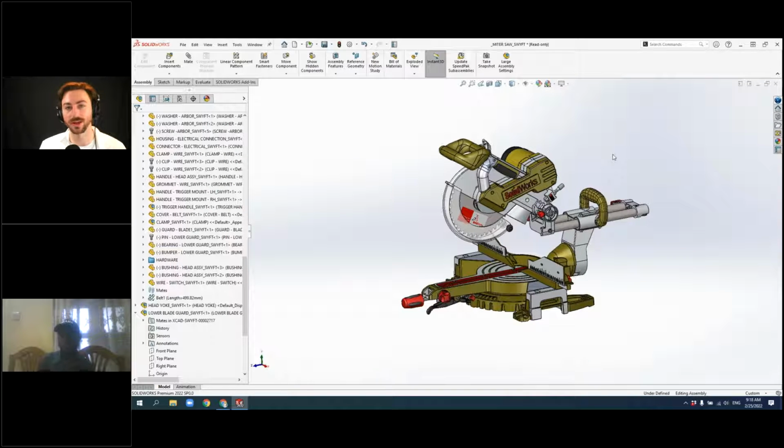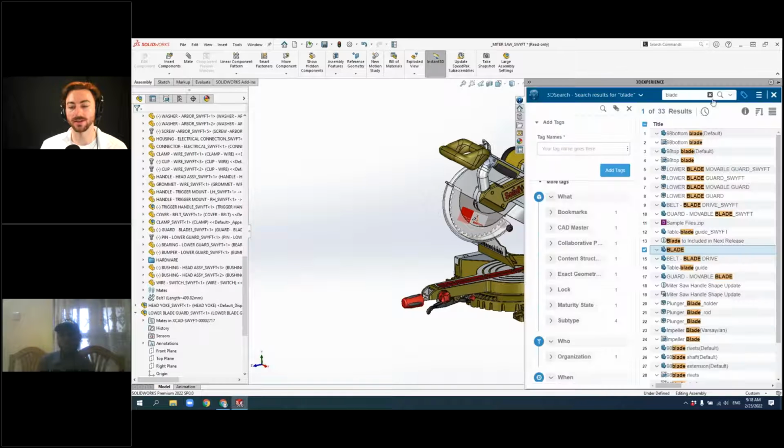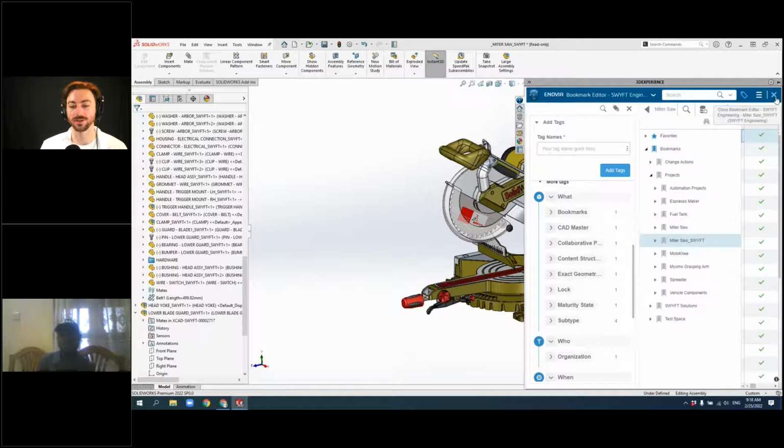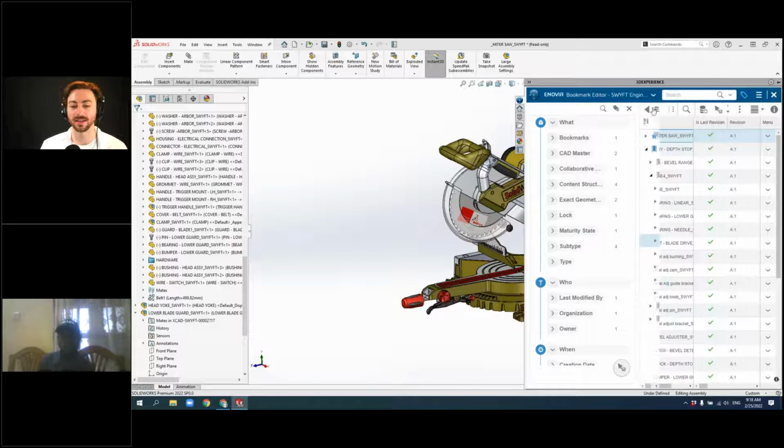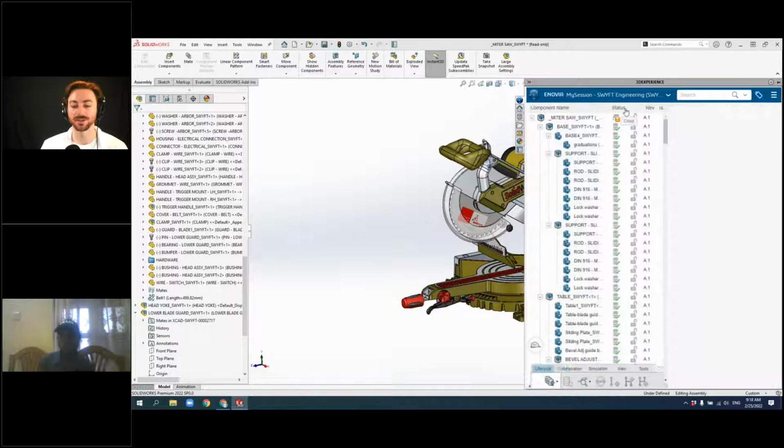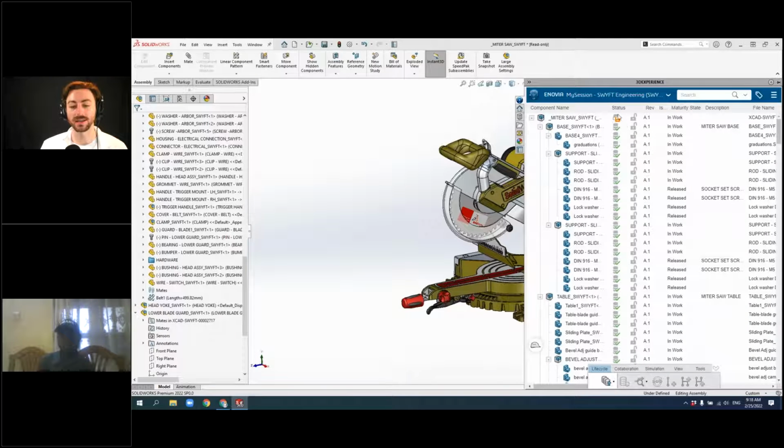If I hit Control S, that's just going to save it to my local cache. But if you're ready to send that back to your cloud-based storage, where anybody else that has access to that database can access the latest version right away, you can come back to your session and see a status symbol here that the file is modified in session.